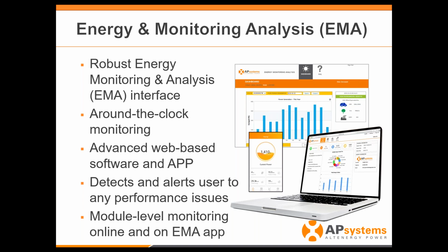One thing I just want to point out, for your benefit for troubleshooting: the ECU itself is the brains of the operation of the AP Systems system. Basically, once the ECU knows its serial numbers, once you scan those serial numbers into the system, that ECU will go out and talk to those inverters every 5 minutes, forever. Let's say you plug the ECU in, that's time 0. At the 5-minute mark, it will say, okay, inverters, what is your status? The inverters will reply back, and that information is held in the ECU's memory.